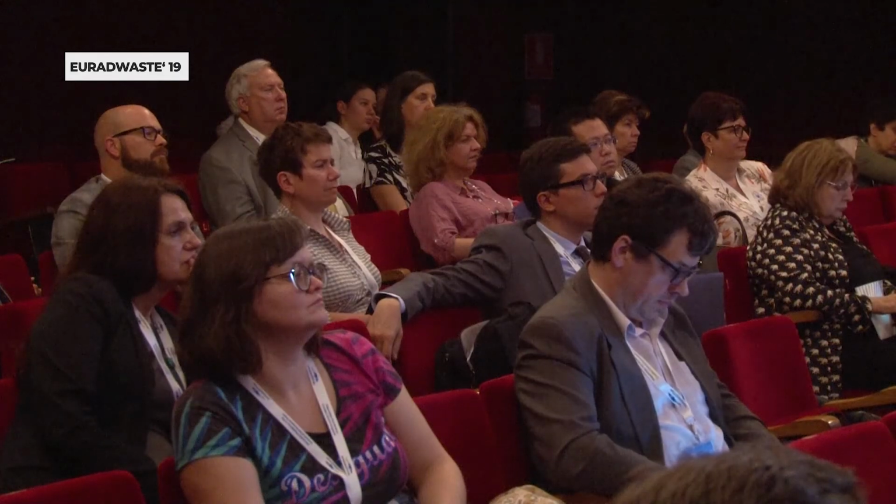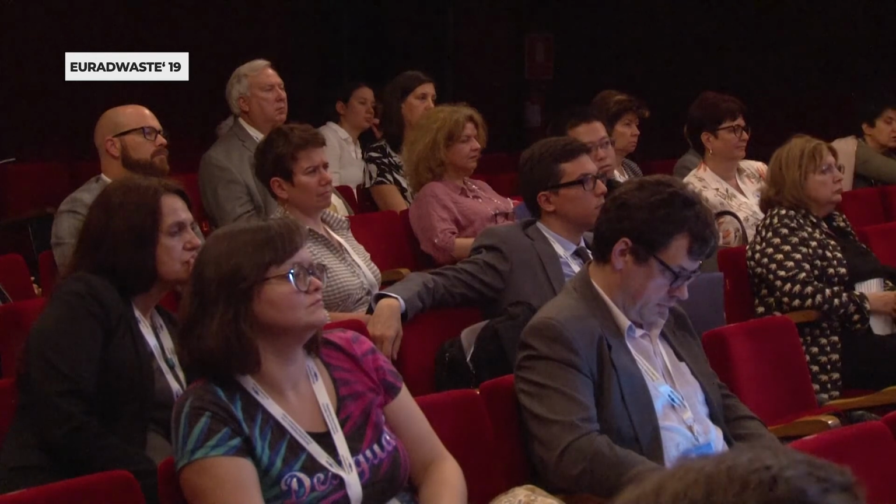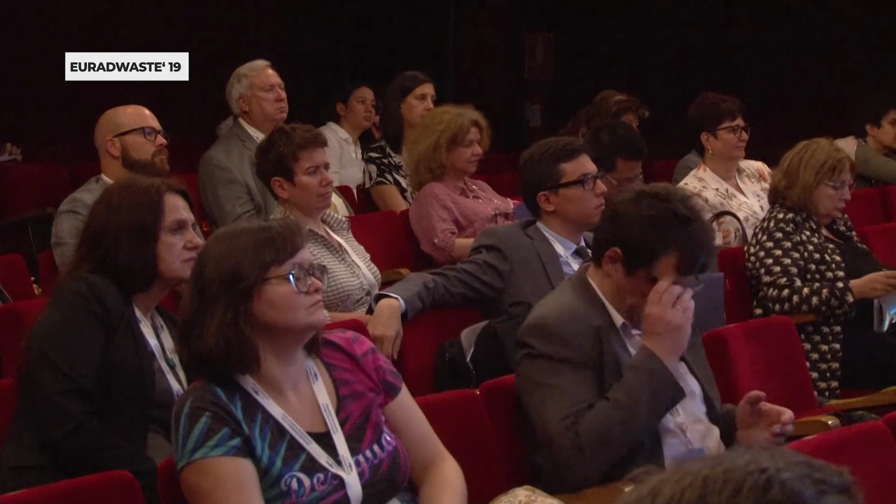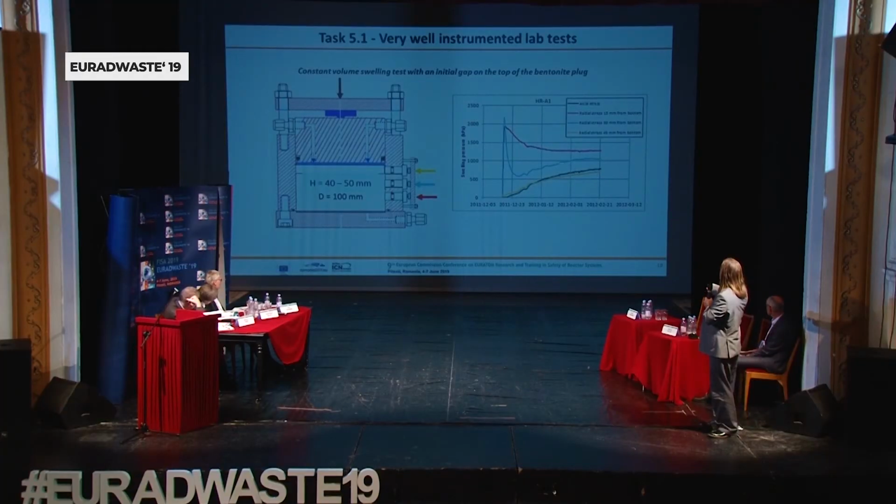The bentonite expands, and here we have the axial stress measured, and we have the radial stress at 3 points. You can see that we don't get to full homogenization, but the stresses increase very quickly here, and then of course the bentonite expands and it decreases at the bottom and the middle radial. And we thought that this is simple, but